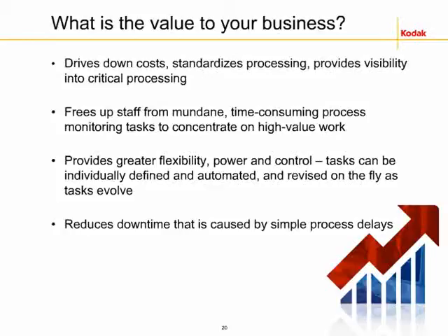So if you select your criteria to be 133 surface print on a 067 plate, it's not going to output a 045 plate at 150 line screen. It won't allow that to happen. It's going to just give you a 067 plate on 133 line screen every single time. And that's the idea, and that's really where you start to see the benefits of an RBA system to a manufacturing facility.